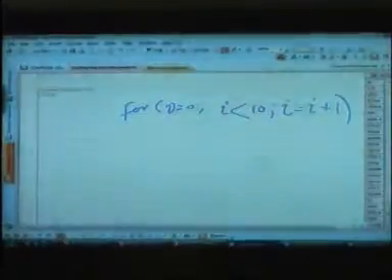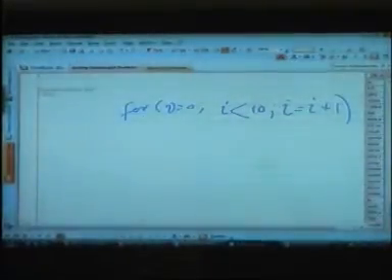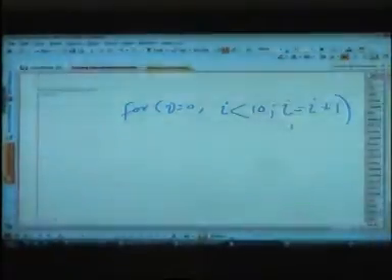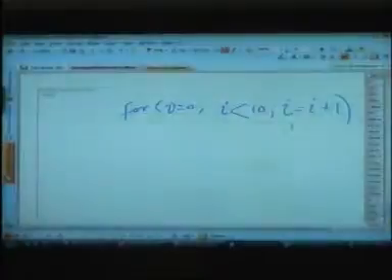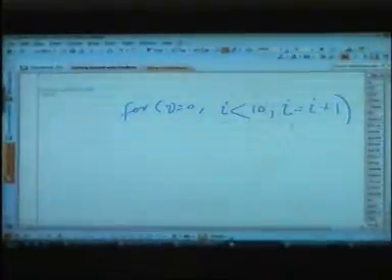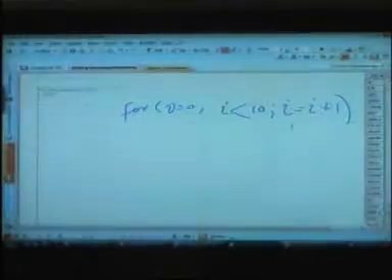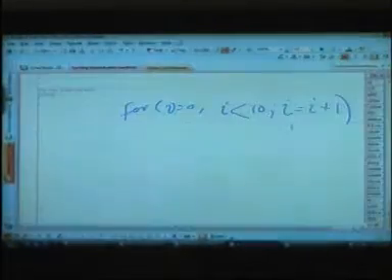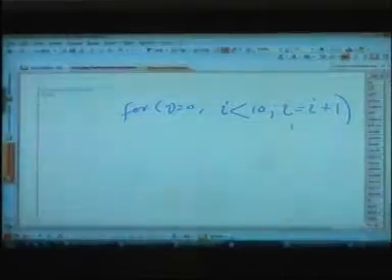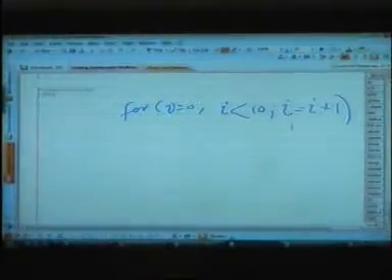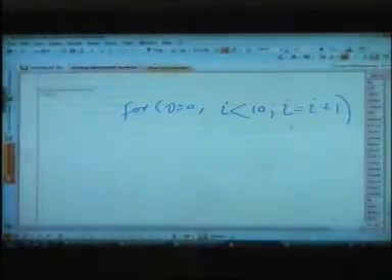It's not the same statement which will run 10 times. It is the convenience Verilog is giving you, that if you are replicating something 10 times, you can put it in a for loop. But it does not mean that the same thing will be running 10 times as it happens in software. That is the difference you always need to keep in mind: calling something 10 times means you are making 10 copies of the hardware. A for loop means 10 copies of the hardware.